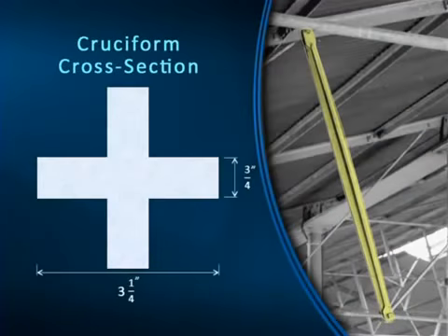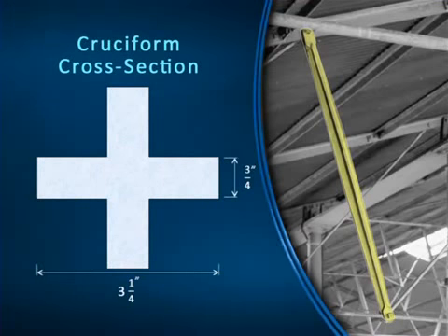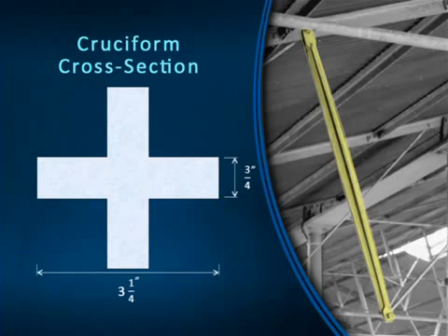As we saw earlier, hollow tubes would be the optimum shape for resisting compression. The problem is, it's very difficult to use a hollow tube in a truss because tubes would have been very difficult to interconnect with the other members that form this triangular framework. So Badger did the next best thing, at least the next best thing with respect to the technology that was available at the time. He used cruciform or cross-shaped members like this, using this specific cross-section dimension. The shape that Badger chose for these compression members does in fact increase the moment of inertia by about 35% in comparison with a solid square cross-section using the same amount of iron.